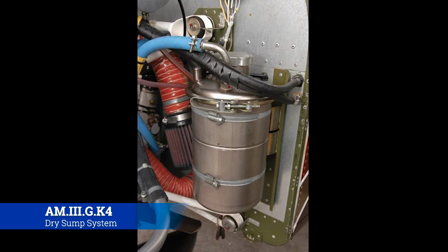Now, all the parts and pieces that we discussed before are still present in both systems. They're just arranged a little bit differently, and arguably, the dry sump system may be superior to the wet sump system, because working on a dry sump system allows you to isolate components and change them out, just like LRUs in avionics. Rather than having it all integrated in one system, you can say, oh, we have a problem with the oil tank. We just change out the oil tank, not a big deal.